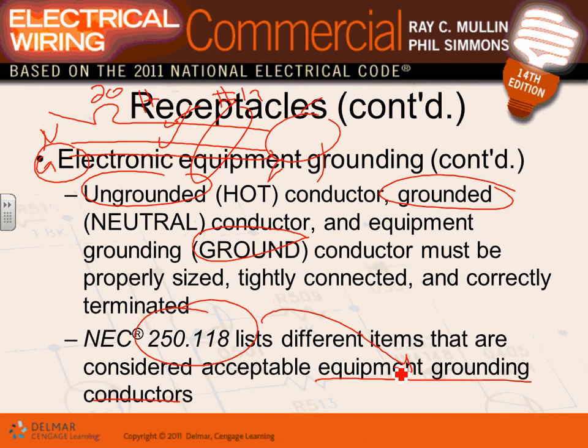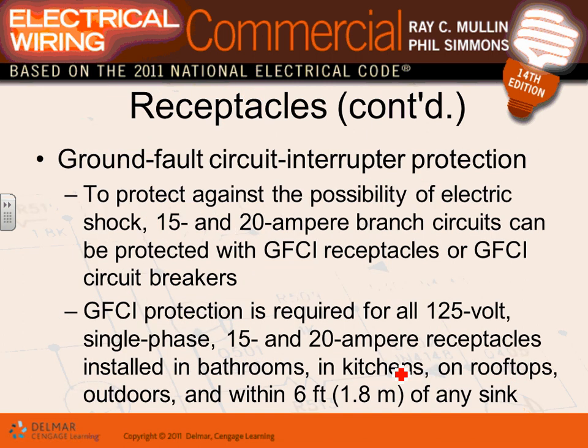So what you do, if you have an isolated grounding system, is you have the conduit to ground the boxes, and you have another conductor to ground the grounding slot of the receptacle. So be aware of that one.